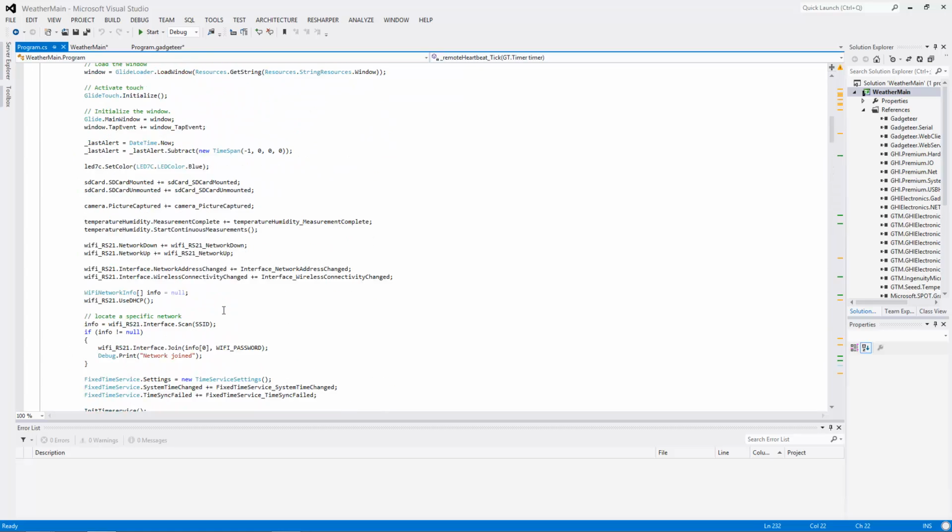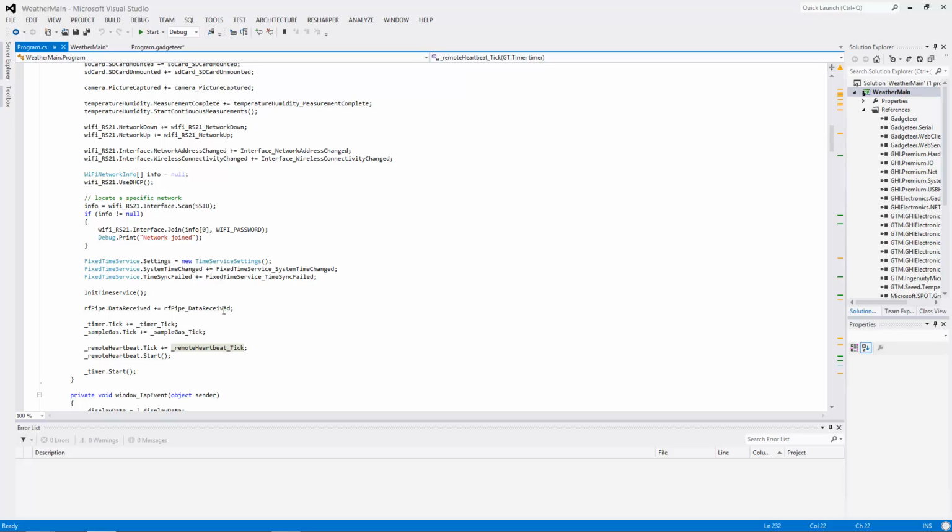Otherwise, there's two timers, and the reason we had to have two timers is because we've got these gas sensors, and these gas sensors work by heating up a coil and then measuring the resistance through them. So we don't want to leave the coil on all the time. That's kind of a waste of power. So what we do is we go 90 seconds with the sensor, the heater coil is off, and then when we want to go get a reading, we fire up a timer, we turn on the heater, then we go 30 seconds, and then we grab a reading off it, and then we turn the heater coil off again.